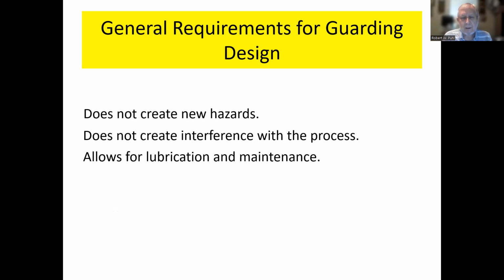So that's very possible. Allows for ventilation. Machines build up heat. That's why expanded metal is probably the favorite of guards, because it does allow for view of whatever's in the machinery. You want to look at the machine, see how it's going, see what's running, see if everything's okay. And you want air to get in to keep it cool.